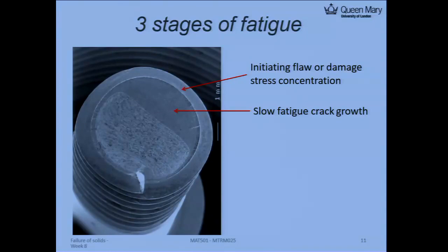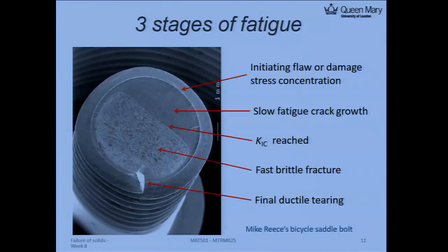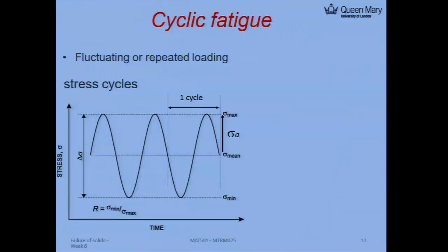the crack tip here. So after a certain amount of fatigue load, you can see some slow fatigue crack growth at this region. You can see the crack surface is very different from either here or the final part, this part. And once you reach the critical stress intensity factor, basically you have a much more brittle failure. So after that is a fast fracture, probably bang, and then you just get completely two pieces of material. Okay?